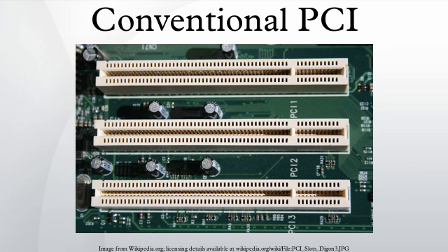Fast back-to-back transactions: due to the need for a turnaround cycle between different devices driving PCI bus signals, in general it is necessary to have an idle cycle between PCI bus transactions. However, in some circumstances it is permitted to skip this idle cycle, going directly from the final cycle of one transfer to the first cycle of the next. An initiator may only perform back-to-back transactions when they are by the same initiator, the first transaction was a write, and the initiator still has permission to use the PCI bus.